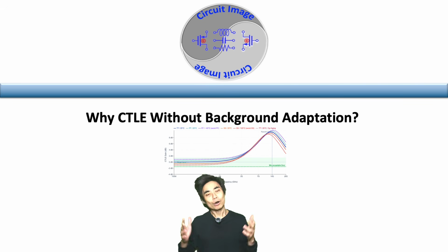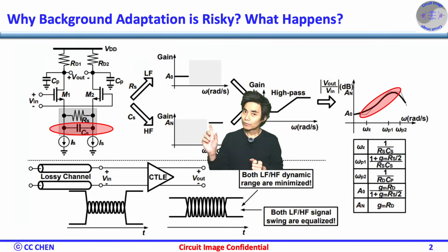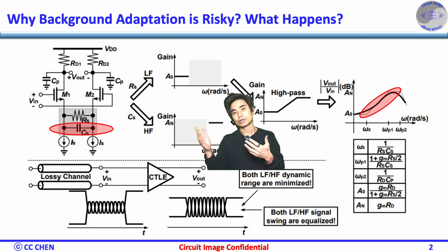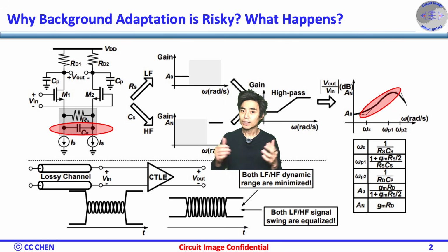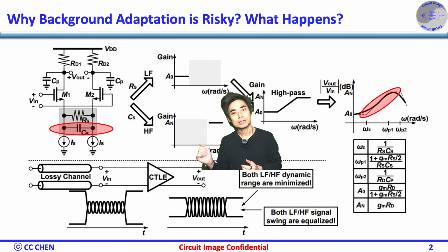background adaptation at all? When you flip a capacitor back or change a degeneration resistor, you don't gently move a pole, you jump it. That creates an impedance discontinuity and a transient in the signal path. At 112 gig PAM4, even a short transient can produce a burst of errors. The slicer sees garbage, the DFE updates on the bad data, and the CDR phase detector gets confused.